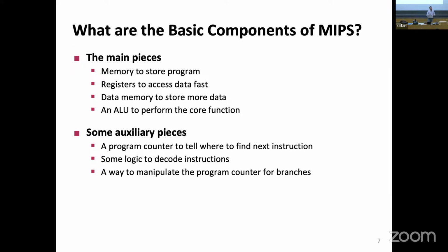Now, normally, if there is nothing else, we will just jump to the next location in the memory, which is 4 addresses more. But sometimes when we have a branch, when we have a jump, we may want to jump to a different address than immediately the address that would have normally come. So we will see these things, and we are going to join everything together and make one great processor that can execute already most of the common instructions that we know. And we will manage it with a piece of chalk on a blackboard. So if we can do this in a piece of chalk on a blackboard, we can certainly do it also using Verilog and other things.